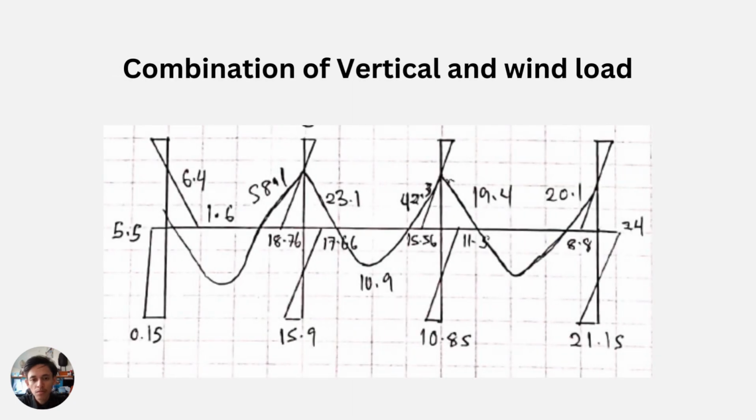For the last part, we can combine the vertical load and the wind load. After that, we can sketch the shear force and bending moment diagram for the combination of vertical and wind load.